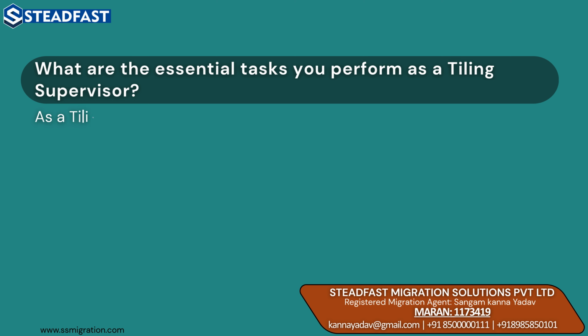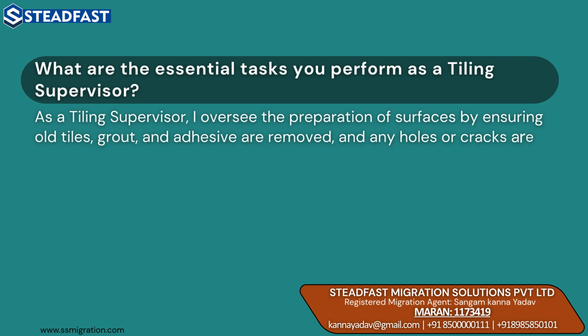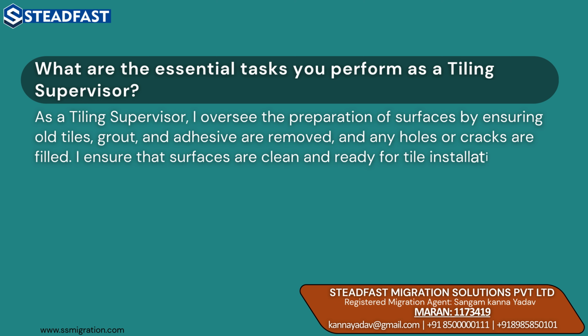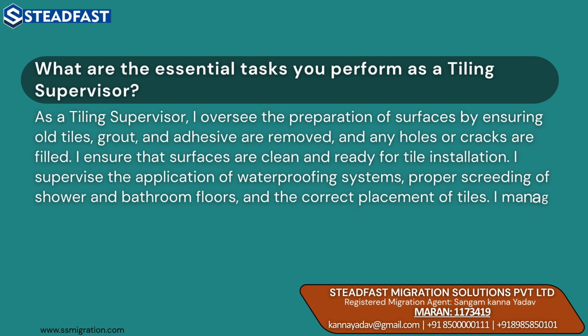As a tiling supervisor, I oversee the preparation of surfaces by ensuring old tiles, grout, and adhesive are removed and any holes or cracks are filled. I ensure that surfaces are clean and ready for tile installation. I supervise the application of waterproofing systems, proper screening of shower and bathroom floors, and the correct placement of tiles.